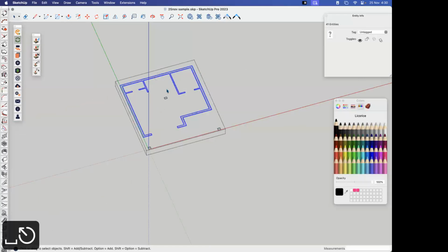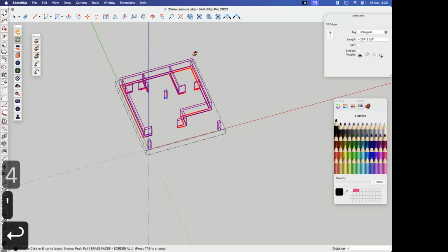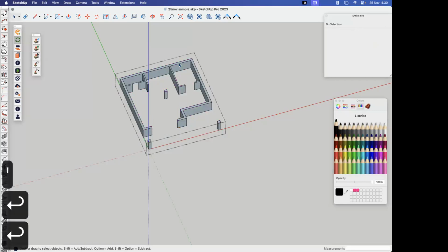So in that case, what you can do is you select all of them. There's this one more component called joint push pull. So in the joint push pull, I'll select the n value, select all the surfaces and then pull them at once. Set the height we have to pull them at, and set the distance and press enter.